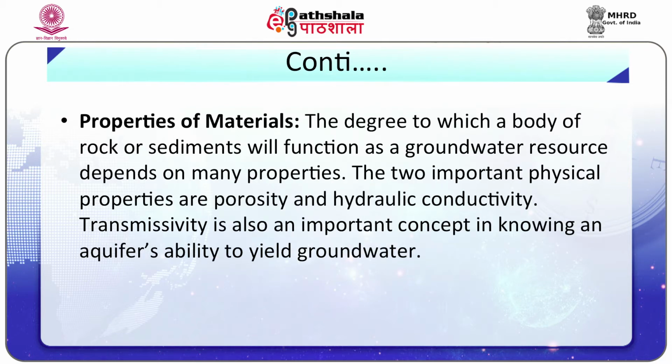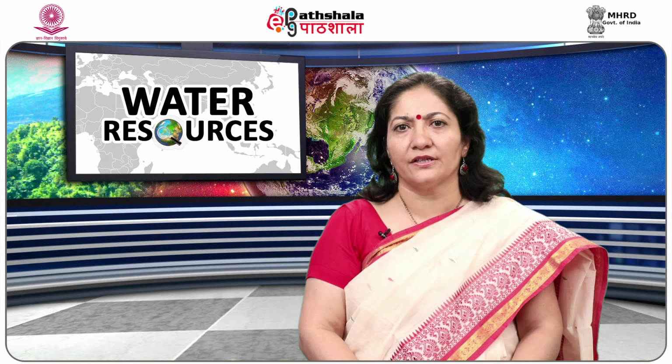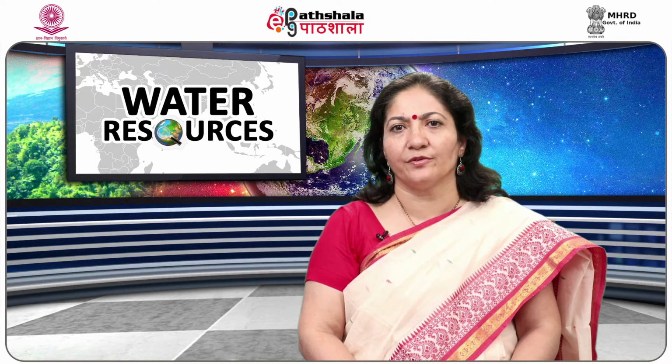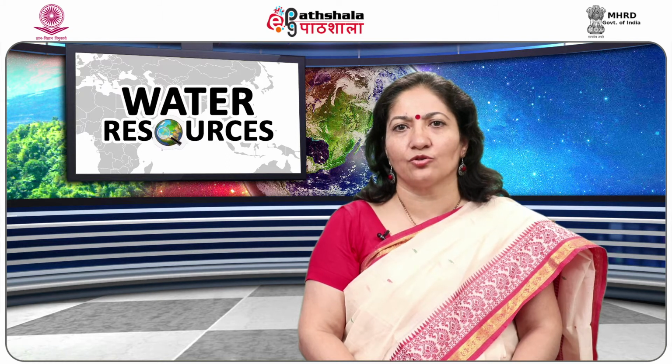Properties of materials. The degree to which a body of rock or sediments will function as a groundwater resource depends on many properties. The two important physical properties are porosity and hydraulic conductivity. Transmissivity is also an important concept in knowing an aquifer's ability to yield groundwater. First, porosity of the rock. It is determined by studying the shape and arrangement of soil particles. It is the amount of air space or void between soil particles. Infiltration, groundwater movement and storage occur in these spaces.